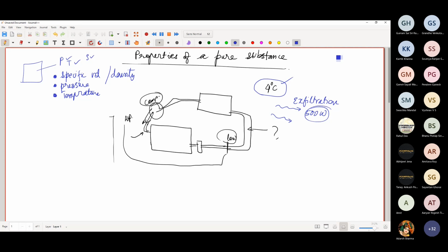No, so basically the answer, I mean, it's not a scientific question per se, but if the chamber is kept at 4 degrees Celsius, you will make the chamber like this, right? There will always be some amount of leakage from the doors, from the seals, and the door thickness will be finite. It cannot be infinitely thick. So suppose outside is 30 degrees Celsius, inside is 4 degrees Celsius. Slowly heat will come in. It will take a lot of time, but slowly heat will start coming in.